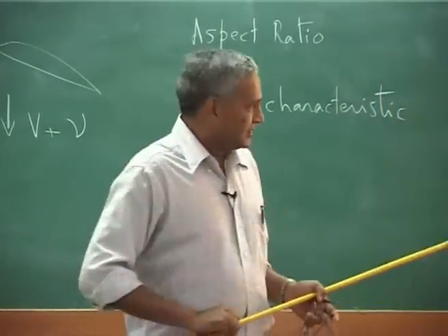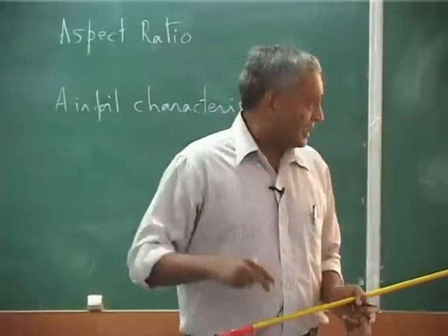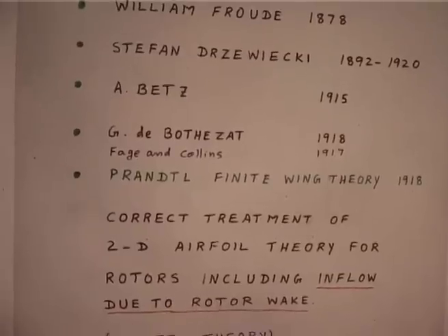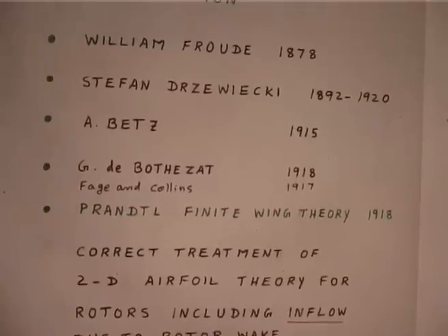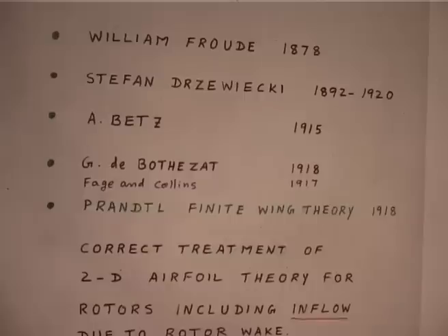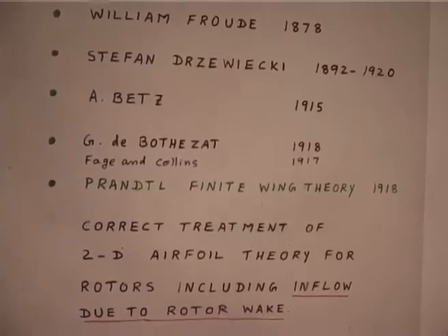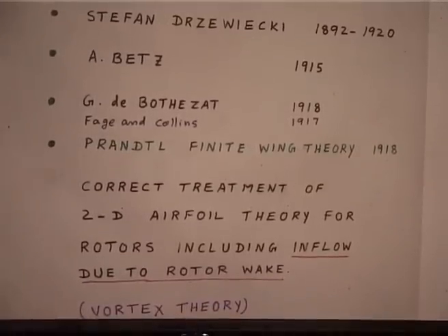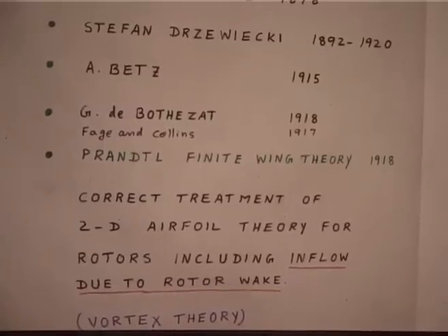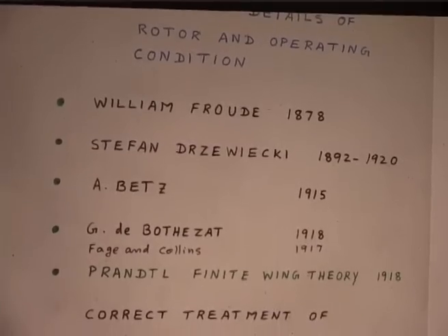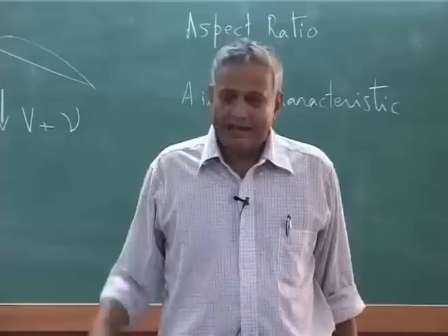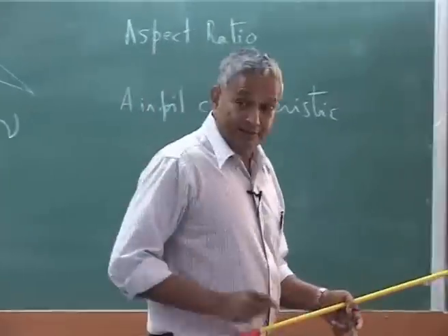But later, Prandtl's finite wing theory, the Prandtl lifting line theory, was proposed in 1918. Then they said, yes, this is the vortex model, because lift is rho U gamma, where gamma is the vorticity, and you find the strength of gamma from the trailing edge. Lift is rho U gamma, and then you take a finite horseshoe vortex, get the strength of the vortex, and then use it.